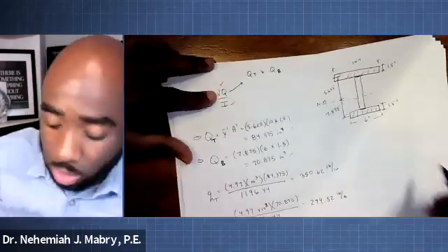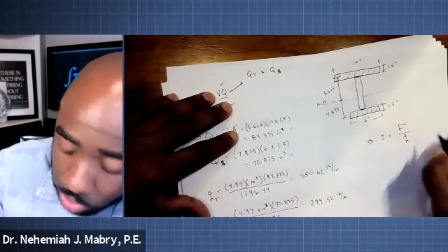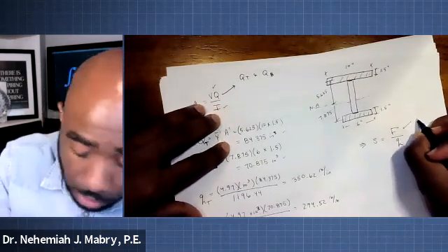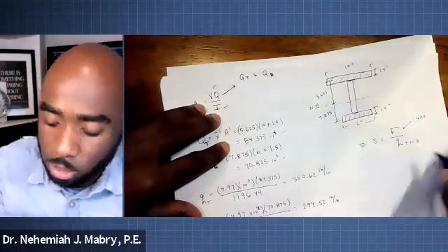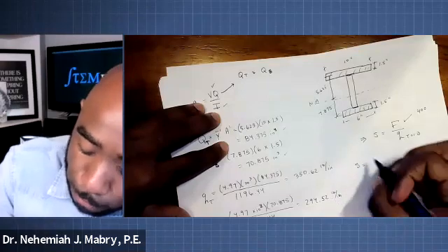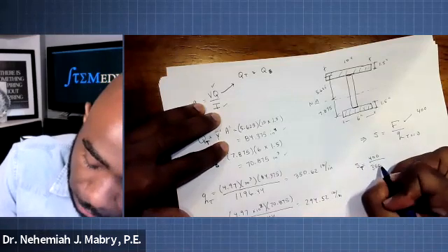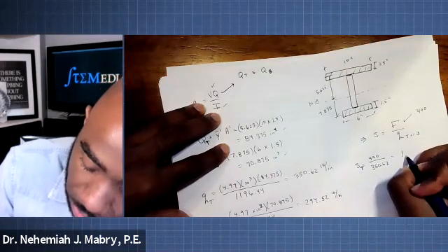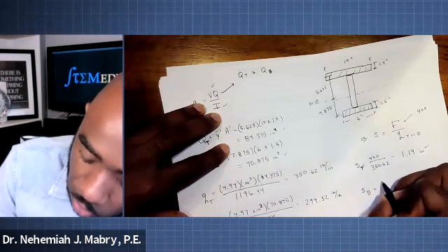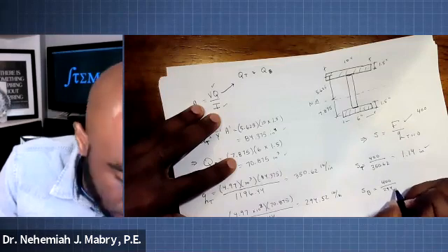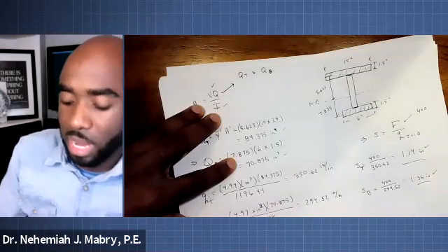And so we use these little q's to find our spacing, because we can rearrange the spacing as F over q. In the problem statement, it told us that F is 400. And this q is either top or bottom, depending on which spacing we want to know. For the top, let's start there, 400 over little q, so 350.62. That should give you a spacing of 1.14 inches to be precise. And then the spacing of the bottom is 400 over 294.52. Those are the spacings to be exact.